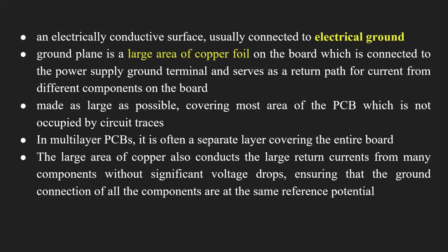If you want to make a two-layer PCB, and both layers have traces, and you also want to make the ground plane in both layers, you will define the ground plane on the top layer as well as on the bottom layer, along with the circuit traces.